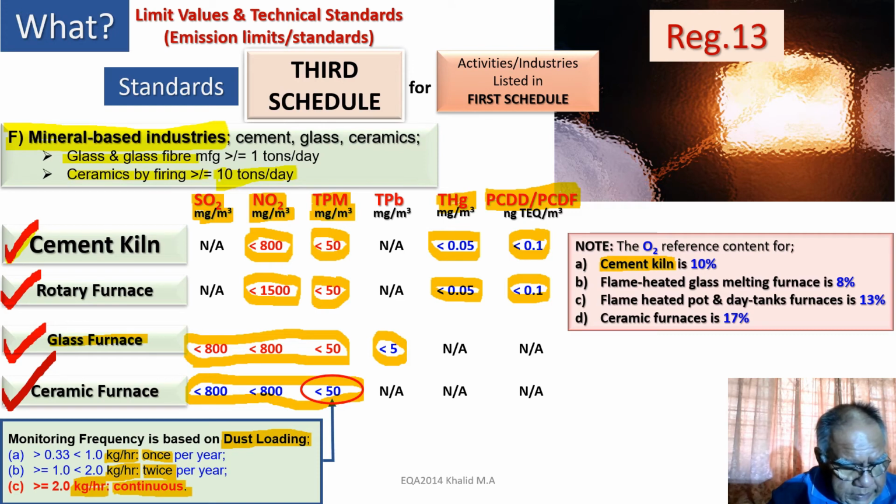There is a note under the law saying that note number 1, glass furnaces, if nitrate purification is required for reasons of glass product quality, sum of total of nitrous oxide NO and also nitrogen dioxide emission expressed as nitrogen dioxide in waste gas shall not exceed a mass concentration of 1000 milligram per cubic meter. It's a footnote for this particular regulation. Number 2, the best available techniques to further reduce emissions, particularly by using improved combustion, shall be applied. That's part of the TOR as well.